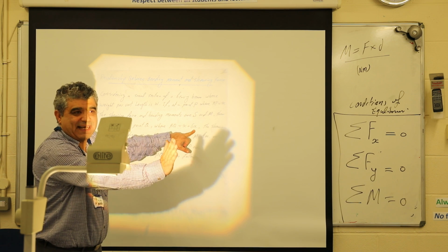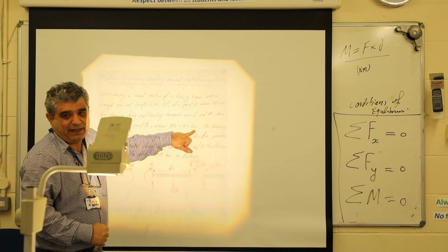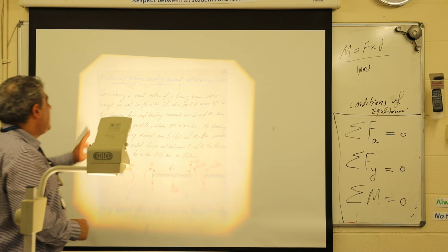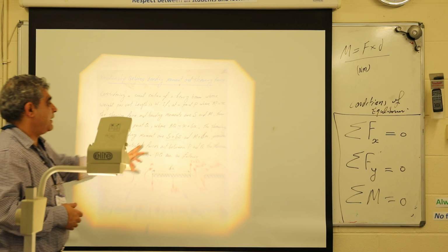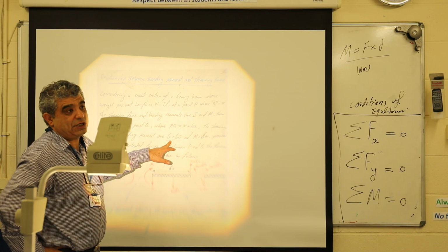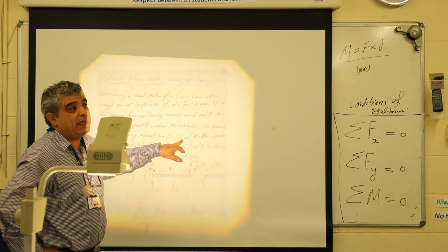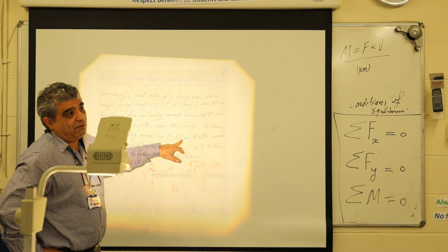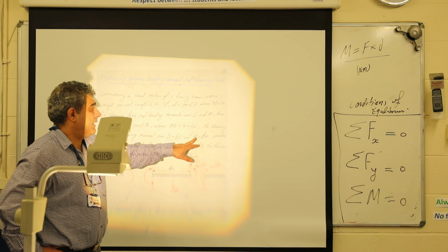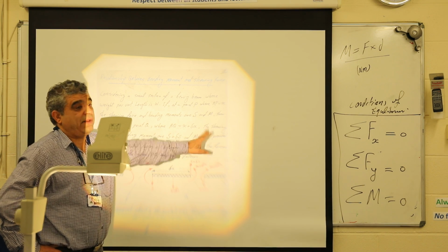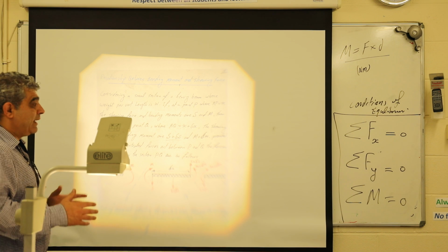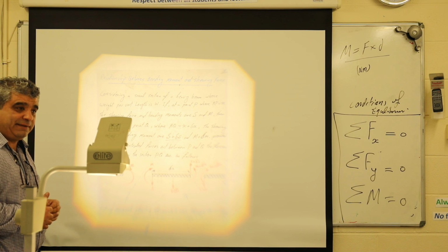Now I'm going to go a little bit extra, I call it delta X. Am I right? The shearing force and bending moment are, so that would be a change in the shear force, S plus delta S. Delta means extra shear or subtracting shear, yes? And M will change with a delta M as well. The change will occur because the distance is changing. Am I right?